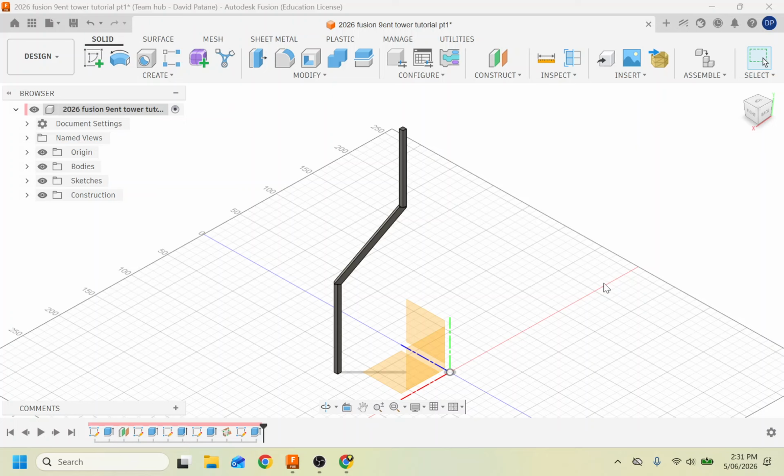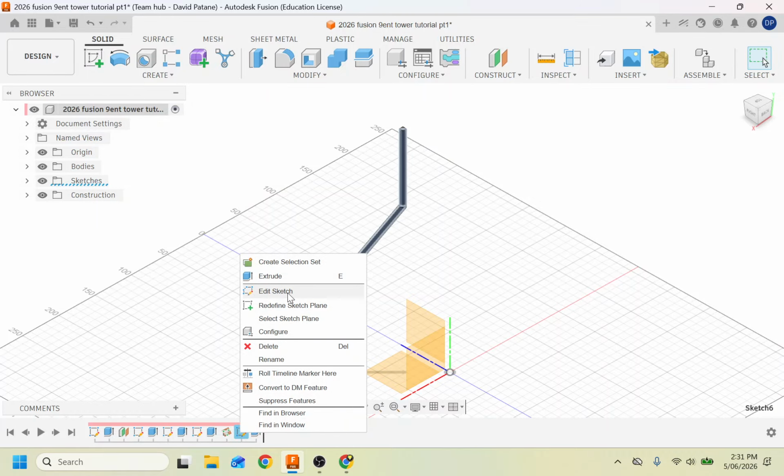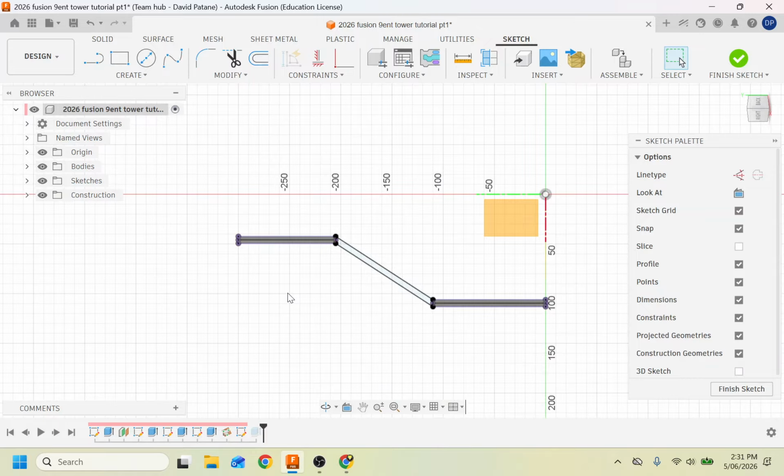One good thing about Fusion is we have down here the timeline. Right? And the timeline is every action we've taken in this drawing. And what this means is if you want to go back and change the timeline, we can. And some things are as simple as if we want to go back and change an individual sketch, we can right click and edit that sketch and change that particular sketch. And then what it will do is redo all the other commands based on that change of the sketch that you wanted. So I'll do something ridiculous, for example.